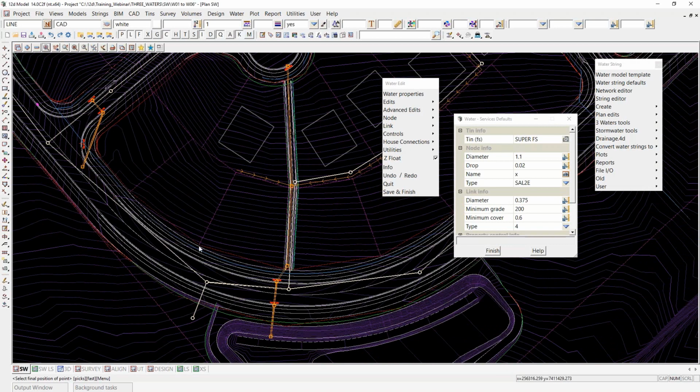Okay. Again, I want to ultimately turn the corner here and make my way down to this one, but I'm going to need at least one other node before doing that because I'm going outside of the road reserve there. Where to place the node, you could pick a point midway between this one and this one on the curb somewhere. But given that this one is a sag here and the road gets very, very flat in this portion of the design, it's probably better to make the node that you do need probably closer to the downstream sag than the upstream manhole.